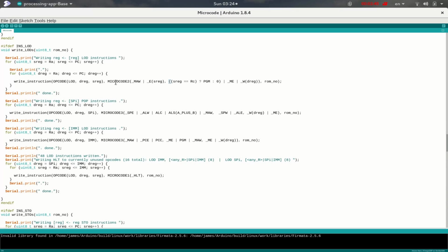But to make sure that our programming environment remains sufficiently flexible, we do want to give the programmer a possibility of reading some random location inside of program memory. And so what I've done here is I've given special meaning to the C register. If the source operand here, if we are dereferencing an address in the C register and only in the C register, then I will in fact assert the program memory signal in my microcode.